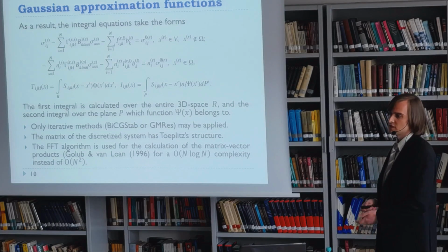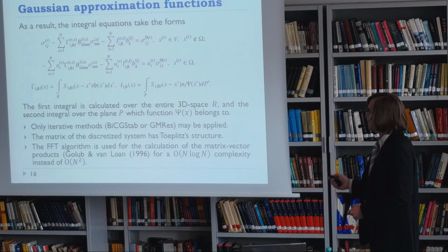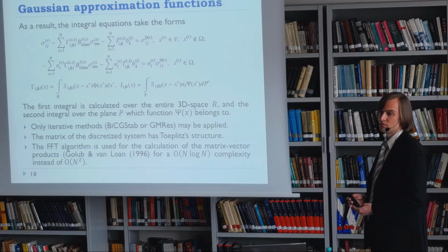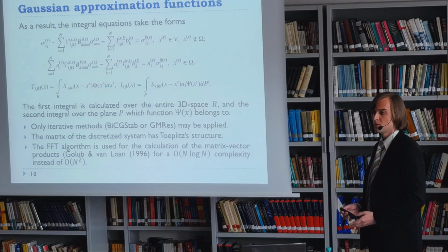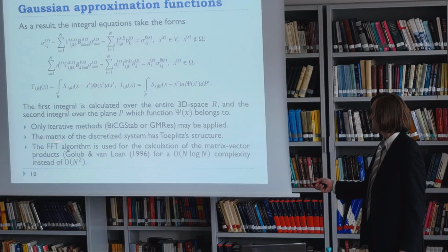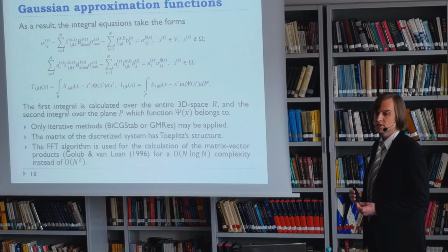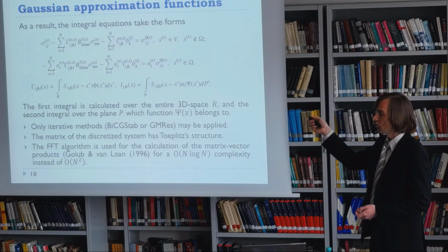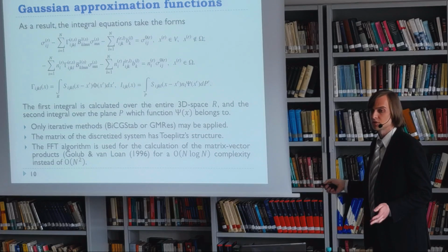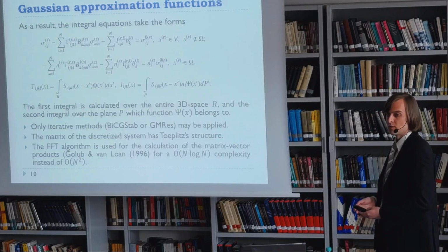Of course, this system can be solved by normal methods, so we may apply iterative techniques for the solution of it. I have mentioned that the node grid we apply for the solution should have a uniform shape, because in this case the matrix of this system of numerical equations would have a triplet structure. It means that we have only one row and one column to store, and that's it. So we may apply a huge amount of nodes for the same amount of memory.